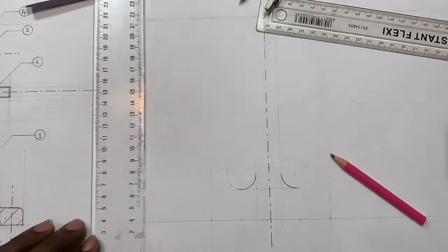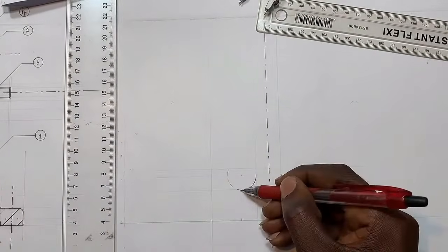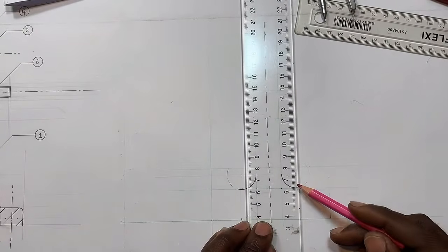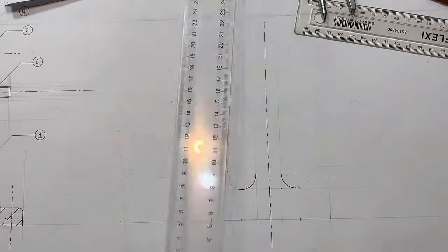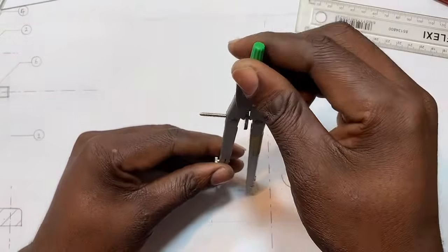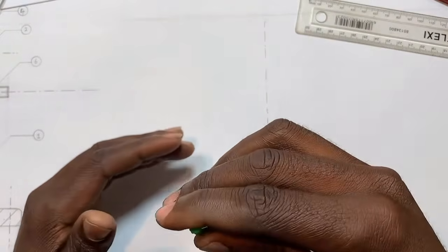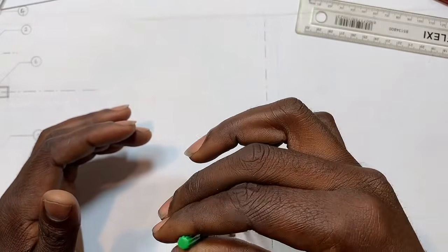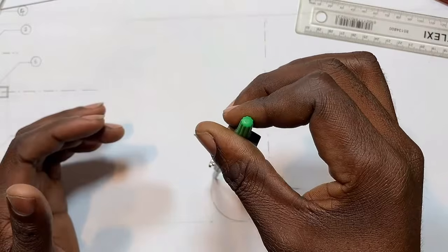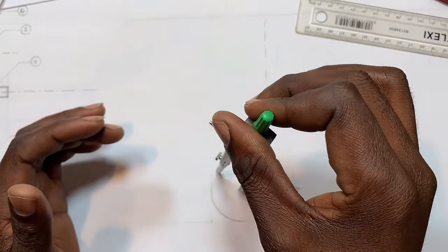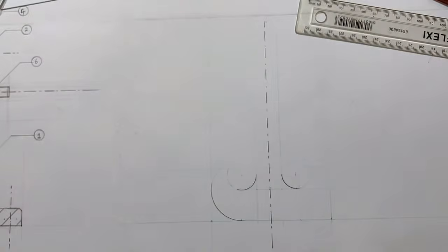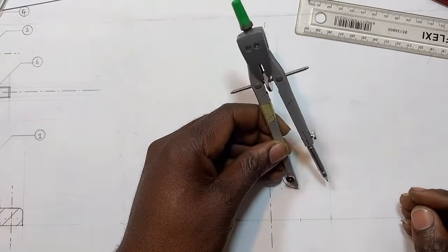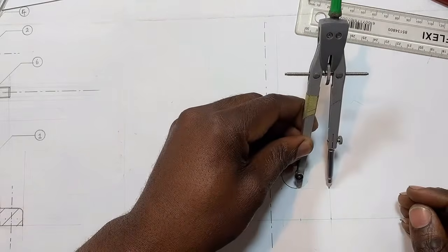So which means I have to place my drawing compass right here so that I draw that arc. Even this other side, simple, straightforward. There you go. So now I place it right here and have this one. So I can draw it solid somewhere here, but I cannot draw it solid yet. Don't draw it solid yet, just a little bit faint to avoid erasing. There it is, which means I have to place it right here. There you go.